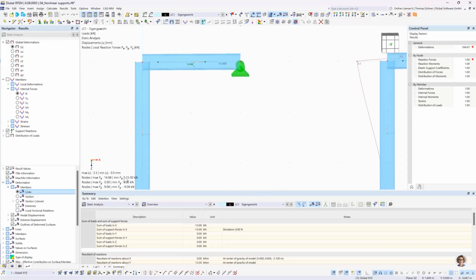It's directed in negative x direction. So there will be a force to that support in negative x direction, and for that support to be able to withstand, or to have zero deformation, it needs to have a reaction force in the other direction. That's why this reaction force is defined in positive.